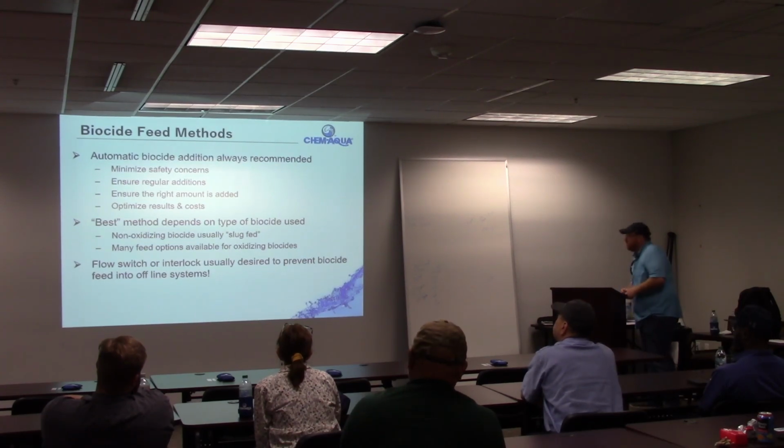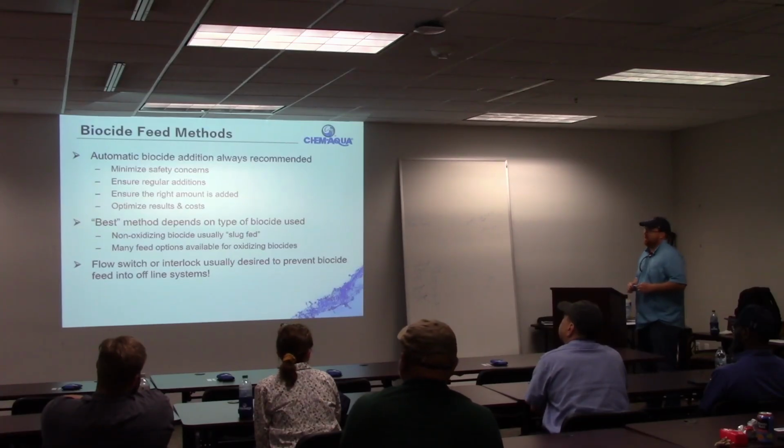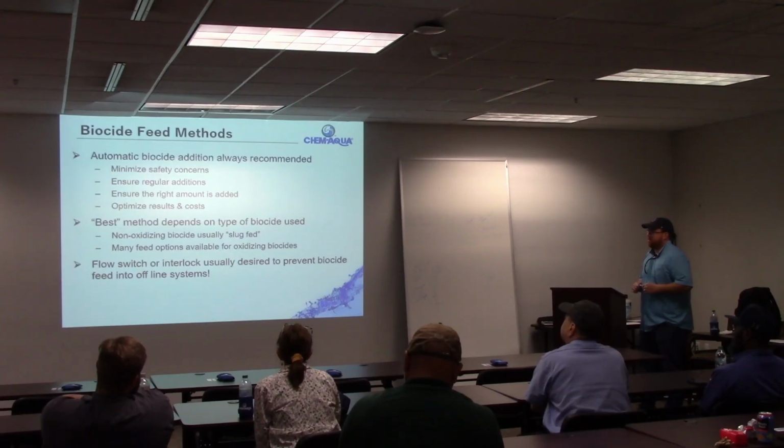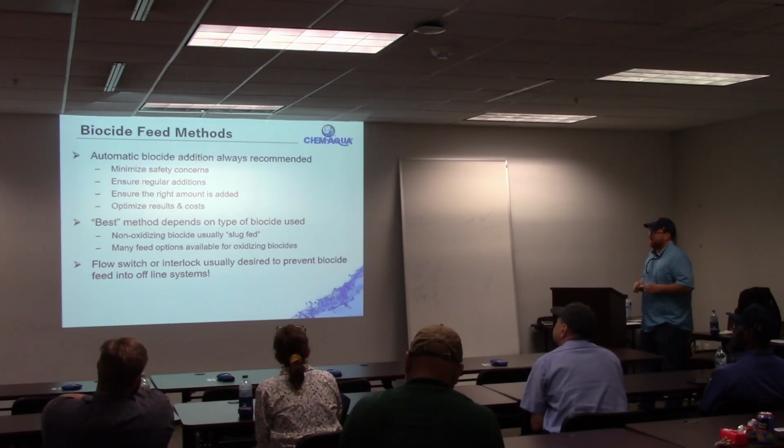All right, so biocide feed methods. Generally, we feed biocide on timers. It's a slug dose. Typically, you're going to feed an oxidizing biocide Monday, Wednesday, Friday. Your non-oxidizing biocide is going to feed Tuesdays and Thursdays, or sometimes just Tuesdays. But that's generally how that's going to be set up.